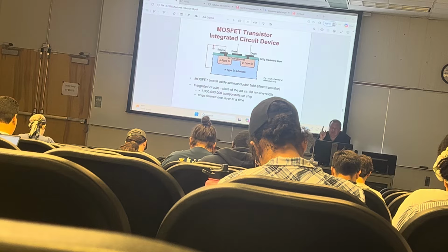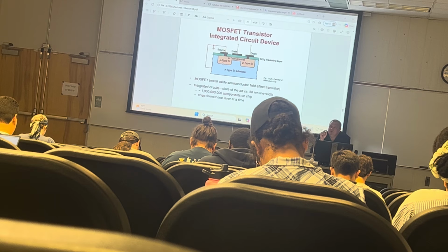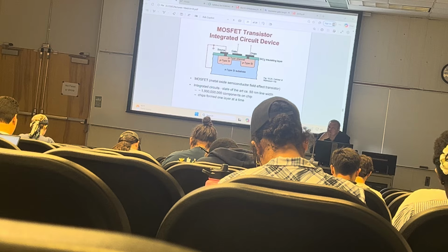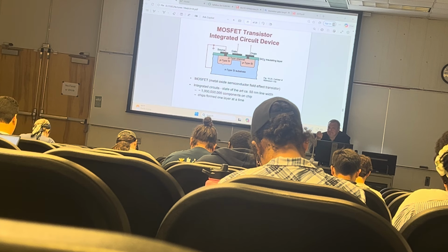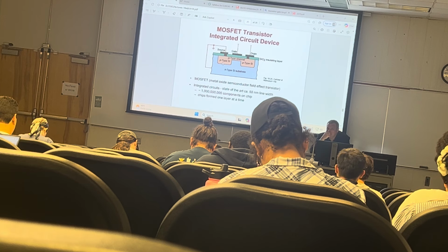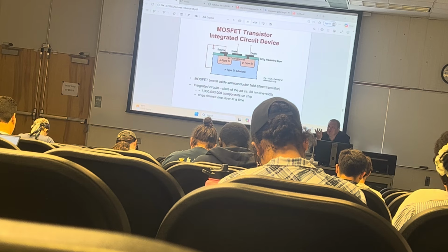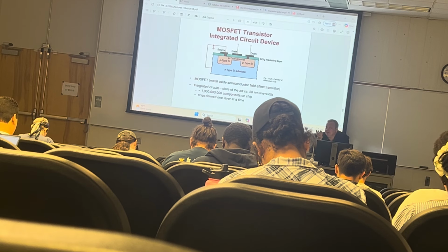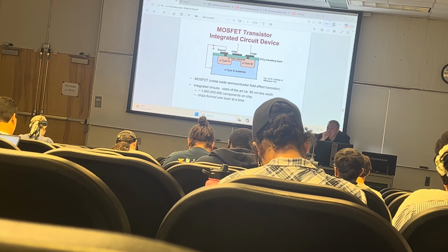There's exponential dependence on what? Two parameters, temperature and time. And we need to do experiments to figure out how long it's going to take, how thick that boron layer has to be. It's called process development.